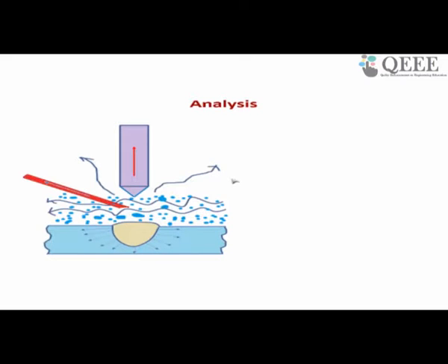resistance welding. Last class we discussed gas welding, where the heat is produced because of combustion of gas. We discussed oxy-acetylene gas welding. Then we discussed arc welding. The principle of arc welding is the same, and depending upon your need, you can use a particular type of polarity and develop any kind of arc. We discussed how an arc can be developed, and that arc welding processes are classified into two types: consumable and non-consumable type arc welding processes.